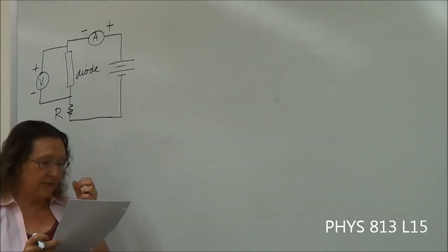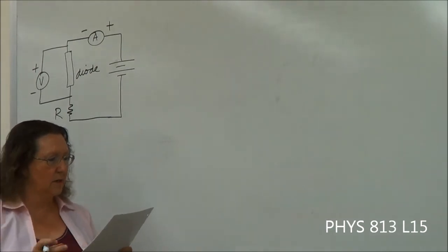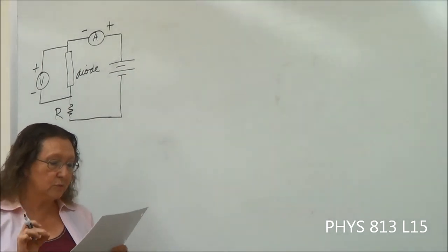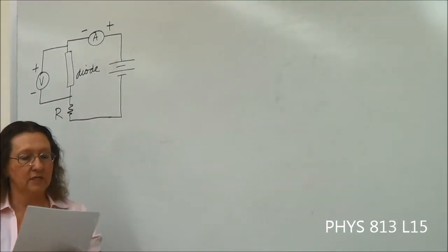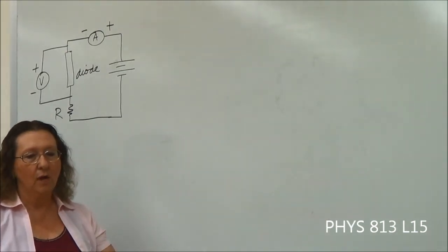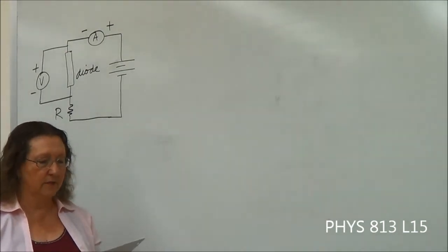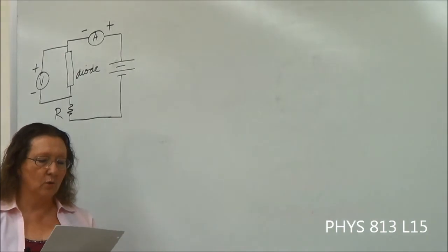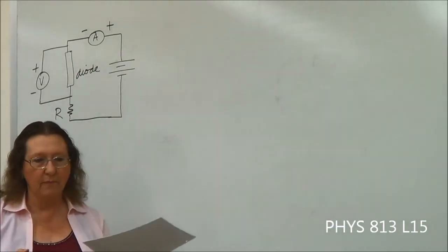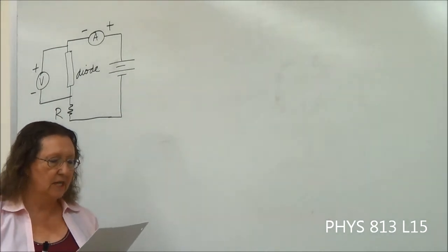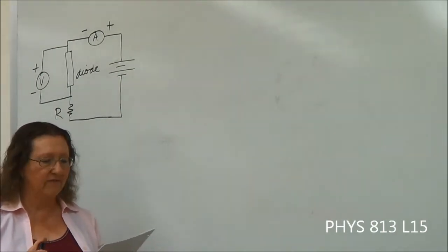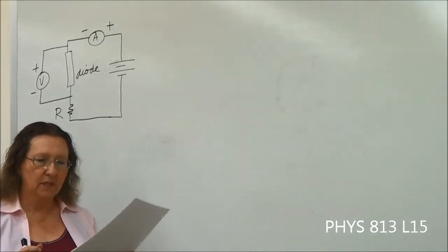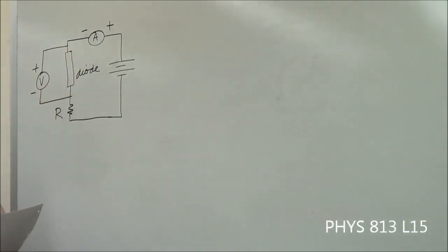Okay, two or three things to note, and this is in step 2, that you really do need to actually kind of pay attention to this. I know sometimes it's pretty easy to think, well, I did the other one all right, so I know how to do this, but there are a few slightly different things. The first one is that the orange DMM that you were using for measuring current or voltage, some various things, it should be set on the 20 volt scale, and you'll use that to measure voltage. Now, the other thing that we need to measure is current.